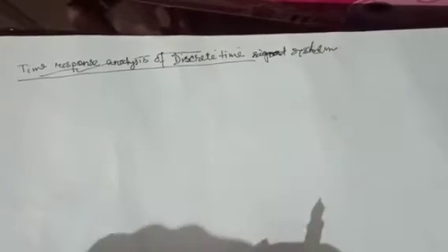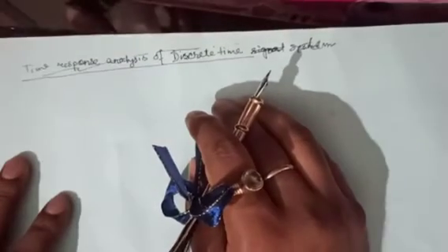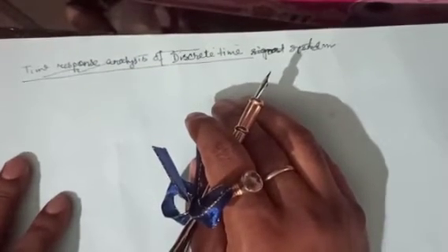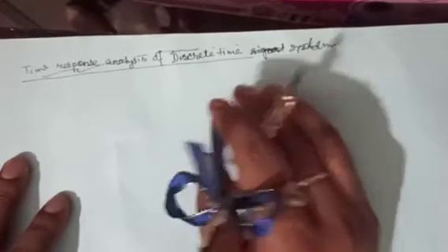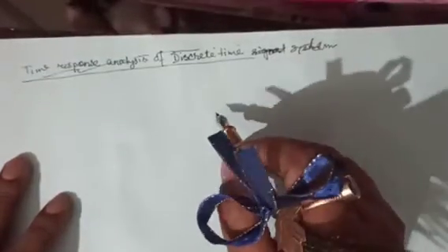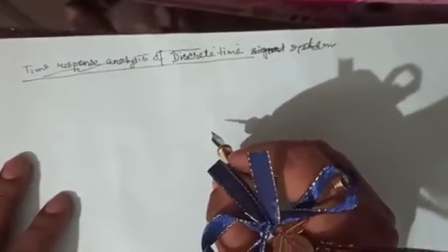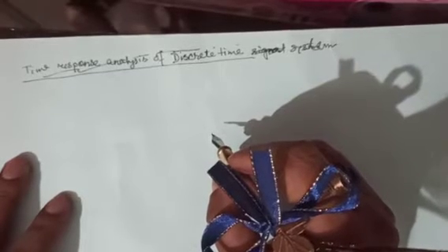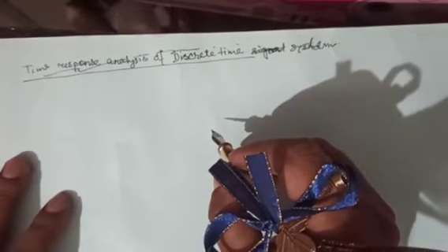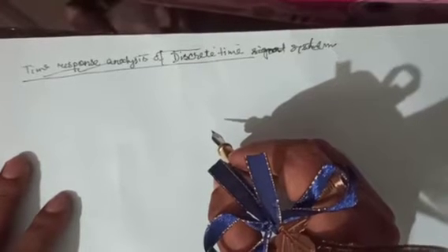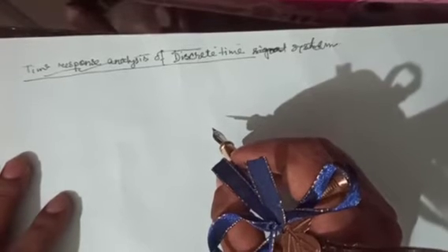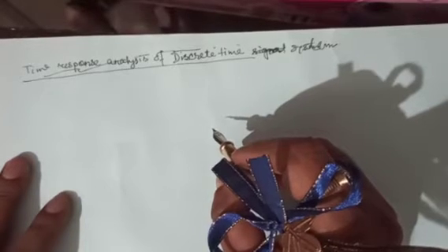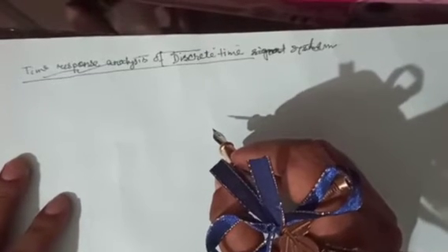Okay, this we have already studied while we derived the convolution. This is nothing but the convolution, because convolution is based on the same concept. If you know the impulse response of the system, because impulse response is nothing but the response of the system due to an input impulse, then you can calculate the response of the system by convolving any arbitrary input with the impulse response of the system.